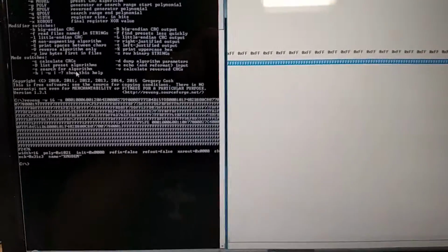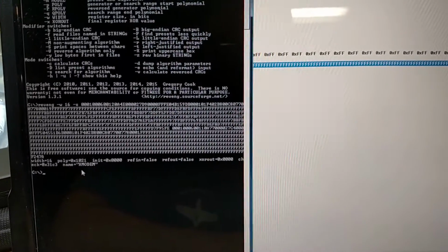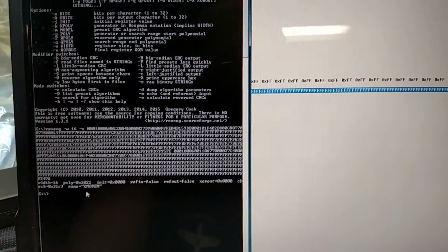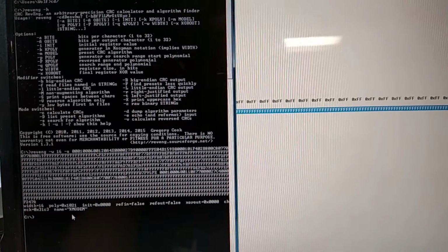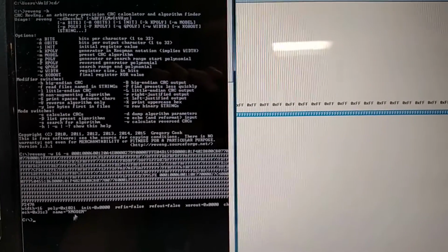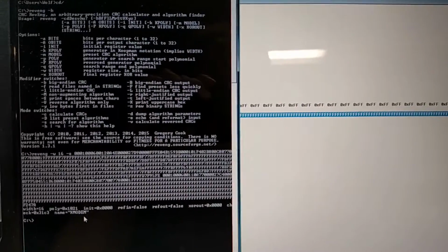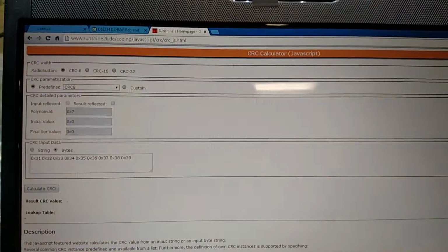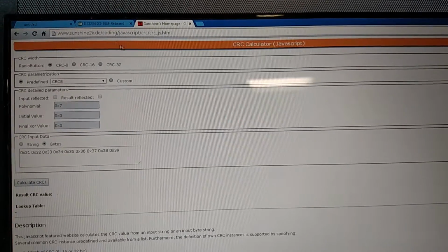We hit enter, and it calculates our checksum, calculates our CRC16 as being the XMODEM standard. So if you watch the Nissan Leaf BMS, where I did the same thing to calculate the checksum in that, they rolled their own, so it was a completely non-standard one. This one, they've decided to actually use a standard, so the polynomial is 1021, and it happens to be called XMODEM.